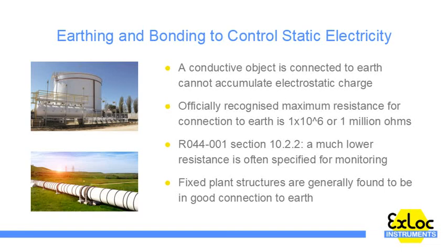If a higher ohm value has been chosen for monitoring, for example to aid with other features such as object recognition, it should be noted that such a system will have the same effectiveness at removing static electricity provided the figure is set below 1 × 10⁶ ohms.